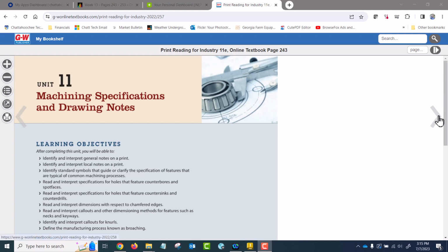You will see in a lot of the drawings from the technical drawing with engineering graphics textbook, those things are noted with the old method of doing things, like neck sizes, keyway sizes, knurls and broaches, and lots of those kinds of things. For two reasons. One reason, those drawings were created under the old standards, and secondly, it's very difficult to dimension an isometric drawing.